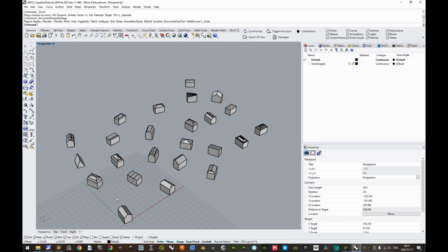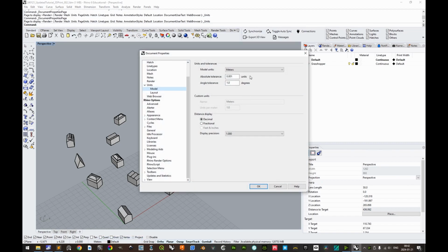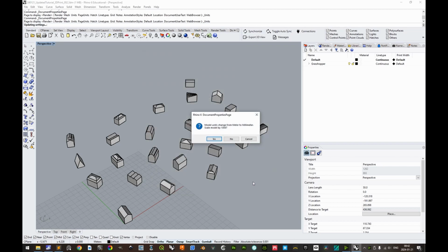The 3D printers use millimeter as their inherent unit for G-code. If you are not already working in millimeters (if you are, you can omit this step), right mouse button click the unit in the lowermost segment and select Unit Settings. Change the model units to millimeters, click OK to confirm, and accept the rescaling of the model so as to make sure that measurements are still 1:1.